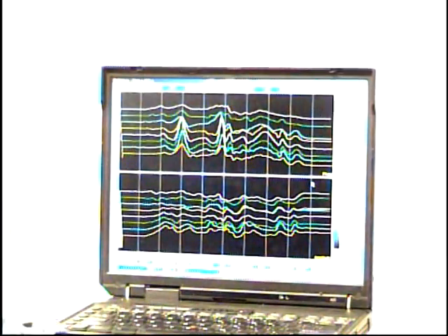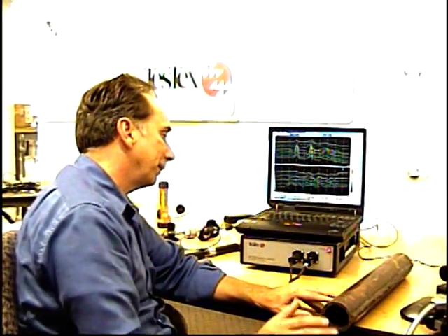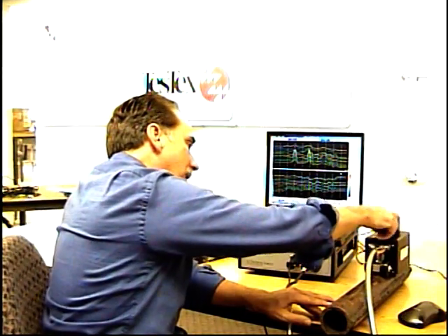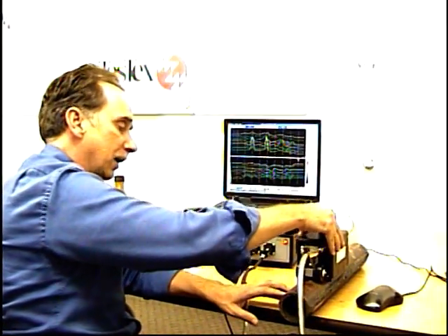Another thing to keep in mind, there are a lot of other companies out there that have a system somewhat similar to this, but one of the most important things to keep in mind about this system is the tube cleanliness. Typically all we need is a water blasting, and that's for your coal-fired boilers, just to knock off some of the loose scale. We want a smooth surface, because we have wheels that scan along the length of the tubes. Most other systems from other companies require sandblasting. Sandblasting can be very expensive, whereas water blasting is a lot cheaper.